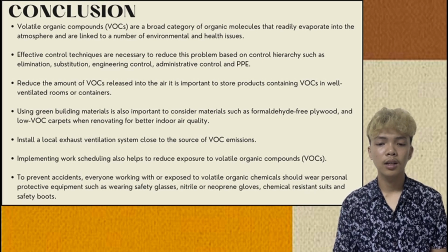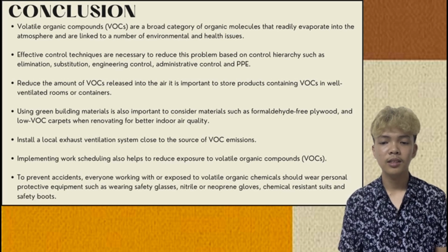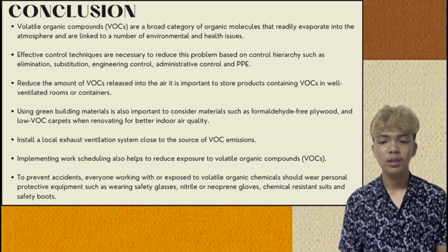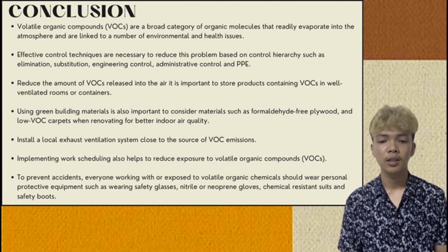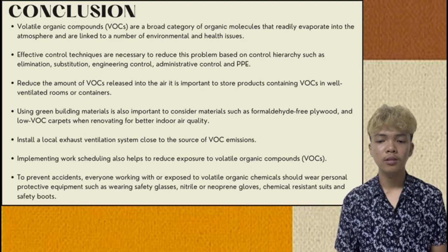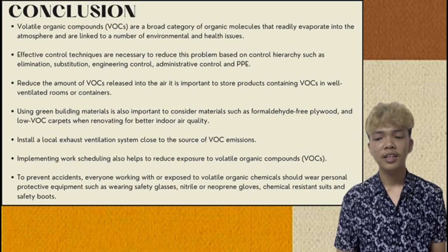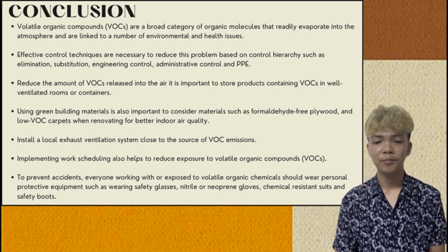Also install a local exhaust ventilation system close to the source of VOC emission. Implementing work scheduling also helps to reduce exposure to volatile organic compounds, in brackets VOCs.